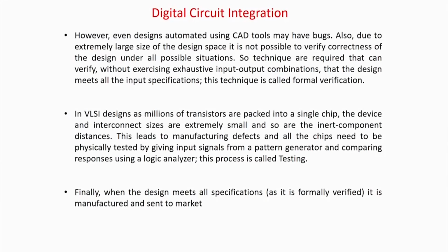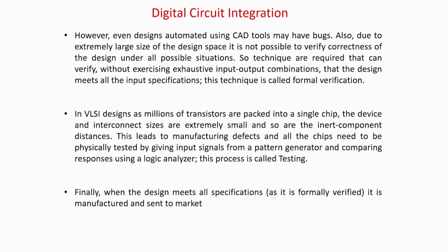Now say you are a very intelligent engineer, you have given very nice block level diagrams and your CAD tool is also very much optimized. So you get a very nice circuit with low area, low power and high speed in a very quick processing time, because everything is optimized, the input and also the CAD tool flow. But again, how do you know the design is correct, as you intended? You give inputs as a high level language like System C or System Verilog, and finally you get a physical layout, that is the transistors. How do you know that your design from system specification to layout has been translated equivalently?